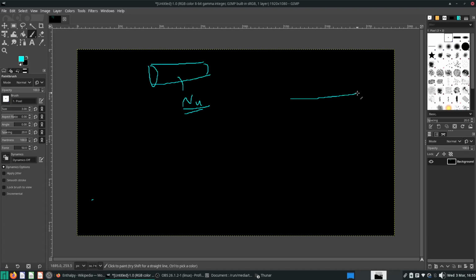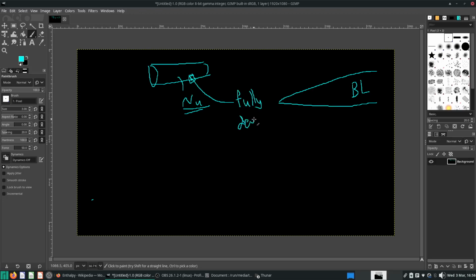But if you really want to understand convection in depth, then you have to look at the boundary layer. In most of the flow, in the middle of the pipe, you will have what is called fully developed flow. But near the entrance region it is not fully developed yet, so you'll have to think about the boundary layer as well.